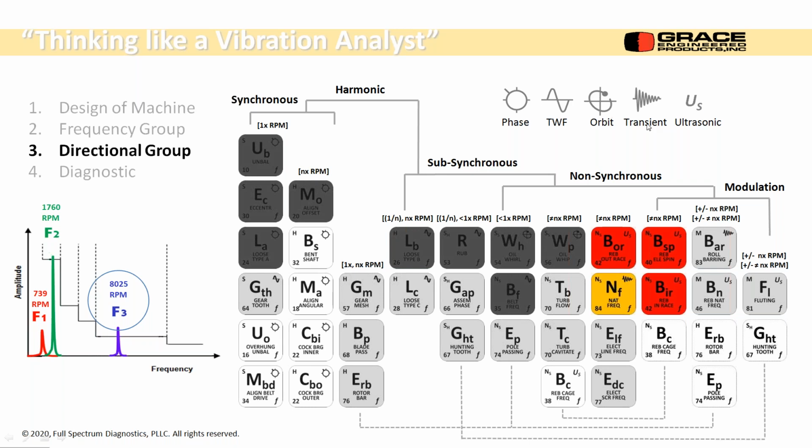Okay. So the diagnostic test inside each of these icons is the test that's recommended, an ultrasonic analysis. So we pull an ultrasonic spectrum and look for impacting in the high frequency spectrum. And then we also do a transient natural frequency test. So there's our diagnostics. And as it turns out in this case, we found that it was an inner race bearing defect.